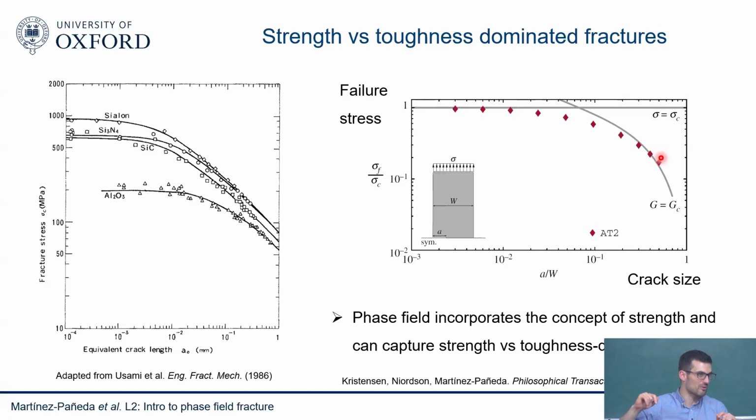I'll discuss a few items now. So then I say, okay, maybe I don't need to use the real strength, because that will require a very small element size. I want to use a bigger element size. You can use a slightly different one and you'll be okay. But in principle, the protocol should be: my length scale is fixed. I can play with the elements, and they need to be small enough. They cannot be that large.